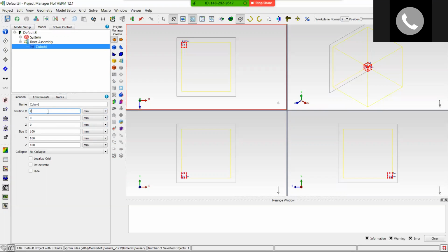Okay. So now let's suppose we have something 250 millimeter by 250 millimeter by 100. Okay. And let's say the position of this is 500 by 500 by 100. Okay, so I just created this cuboid, and that is the structure, and that's the size and location. You can certainly use the GUI to resize it right here, move it, expand, things like that, or you can be specific with a particular number.